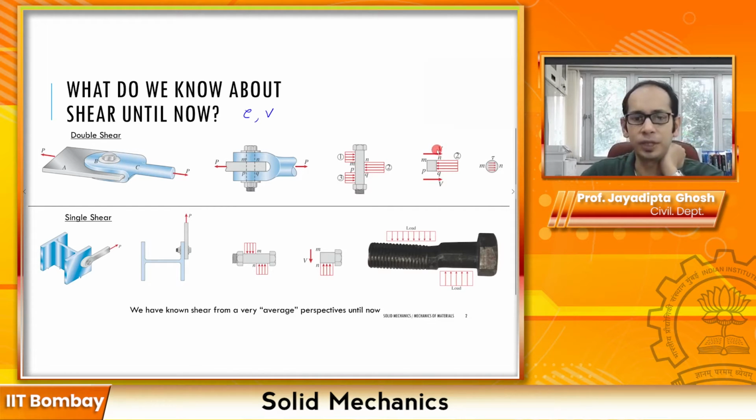That's why when you come over here, you see that at this interface, at these junctures, this is where the shear force acts. It always acts along the face, right? So if we have this bolt, it always acts along that face. And since it acts along the face, this force V that you see over here acts over this area that you see for the bolt. And if this is A over here, then this tau, as we remember, or if you remember even more clearly, we said that it is in some sense the average shear which we are talking about. And in this chapter we will understand why it is called average.